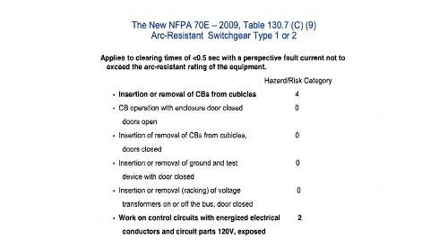This table states that if you're going to be in the cubicle, in the breaker cubicle, you're at level PPE 4. These are generalized requirements that eventually will find their way into the NEC codebook, I might also tell you. It lists the risk and hazard category. Hazard category to NFPA is the PPE rating. All right, it starts at 4, and look at all the zeros. That's what arc-resistant switchgear does.